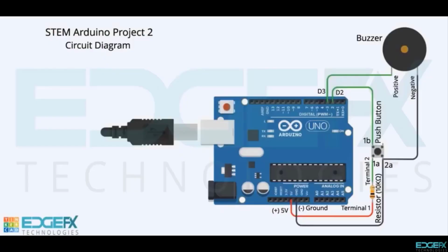Let's demonstrate the push-button switch, buzzer, and generate sound with Arduino sketch. To summarize this step 2, we connect the push-button switch, buzzer, and Arduino such that when Arduino is powered and we press the push-button switch, the buzzer goes on and off or beeps for a specified duration of time and switches off when the switch is pressed again. This action repeats itself whenever the switch is pressed.